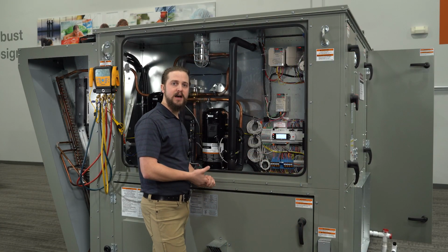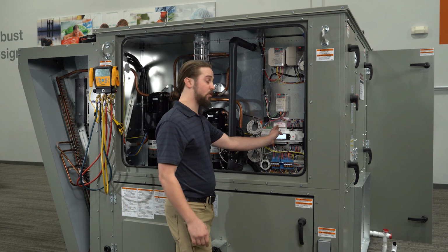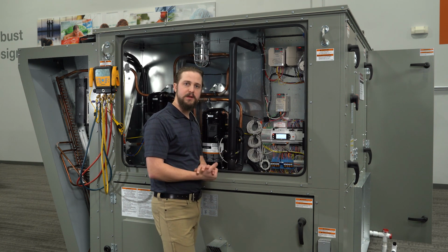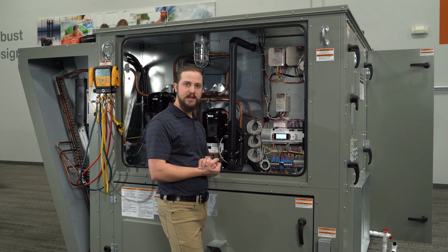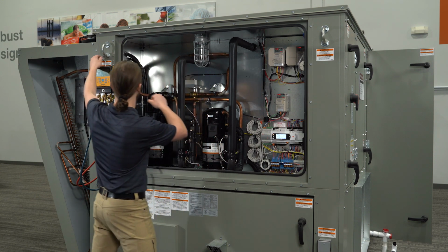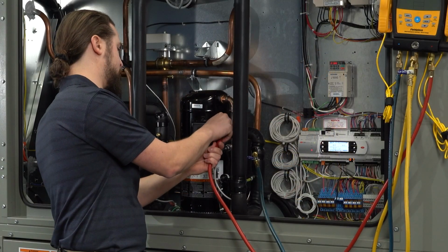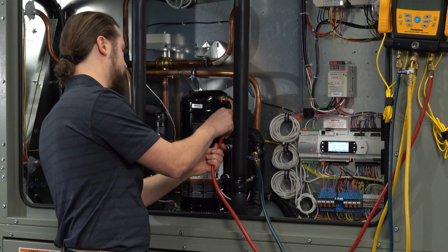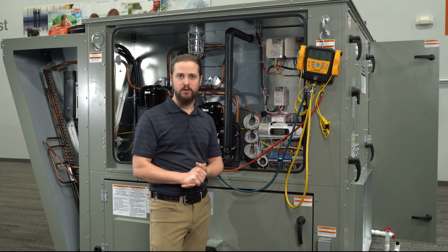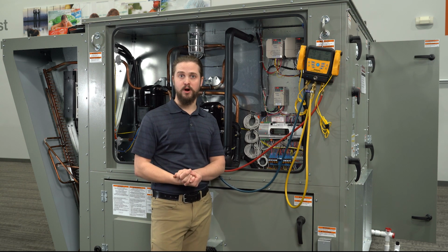Now, if you do not have refrigerant pressure transducers or you can't locate them, you don't see any information in the unit controller, our recommendation would be to get manifold gauges and connect them to verify refrigerant pressure. Let's do that now. If either circuit has abnormal pressure or leads to you suspecting a leak, now would be a good time to give our tech support group a call.